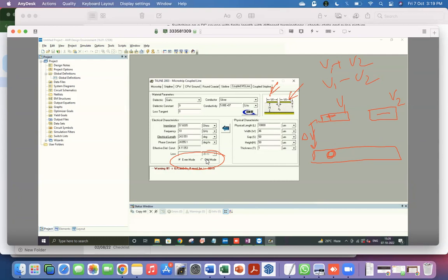Yeah. How exactly do I imagine this even, which is because the voltages are same, yeah, or different, they say even and odd? Yes. So if I now sort of draw a side view, what that means is that if you think of these two as independent transmission lines, which means that you have to write V of Z along the line. For the even mode, they will always be the same on both the transmission lines. For the odd mode, they will be equal and opposite.